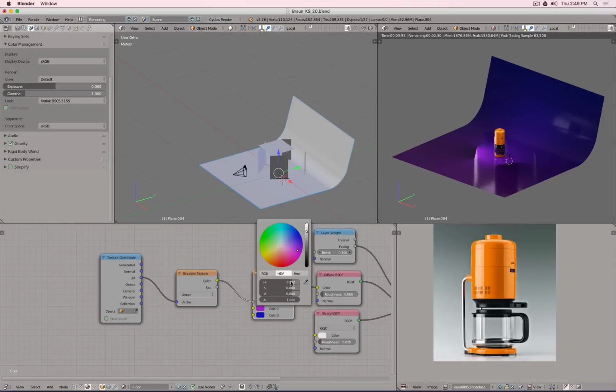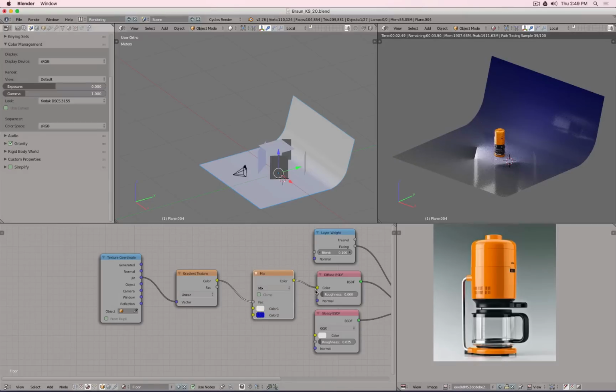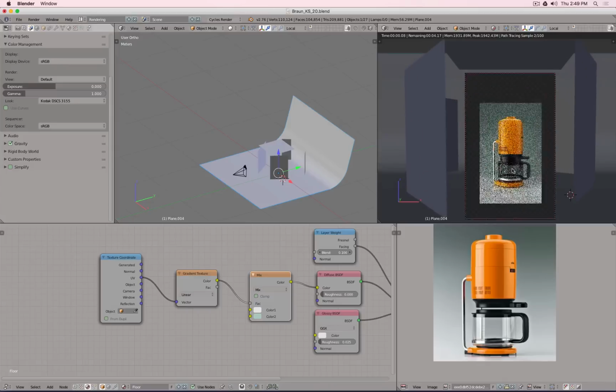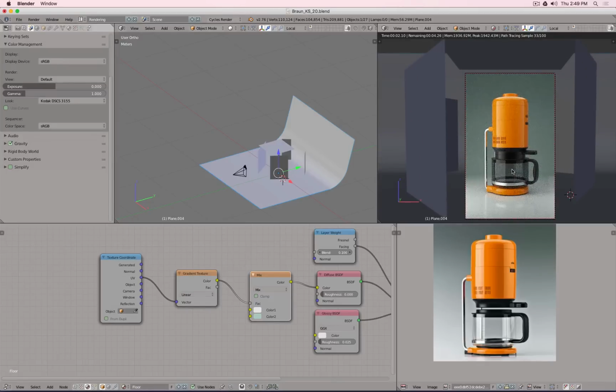Okay, now did I miss? Oh, wrong color mode there. And this bluish is actually the back, so I can drag this one onto the blue there. Okay, let's press 0 to go into the camera and let's take a look. Oh, this is already much better. You see actually how this is white and then it blends into this color. Not too bad. But right where my mouse is, there is kind of like a shadow line.